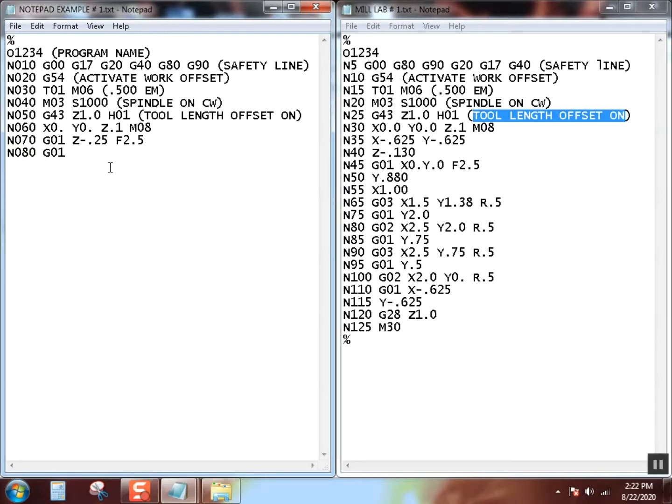Okay, so I've got G01, and let's just say we're going to mill a 2-inch square. And we're always going to climb mill, so that means we're going to move Y. So Y1.0, that keeps it straight. The feed is also modal. In other words, as long as you program it there, it stays that way until you change it. But again, for clarification, I will keep doing this. You don't have to do that. Now's a good time to hit Control S again.